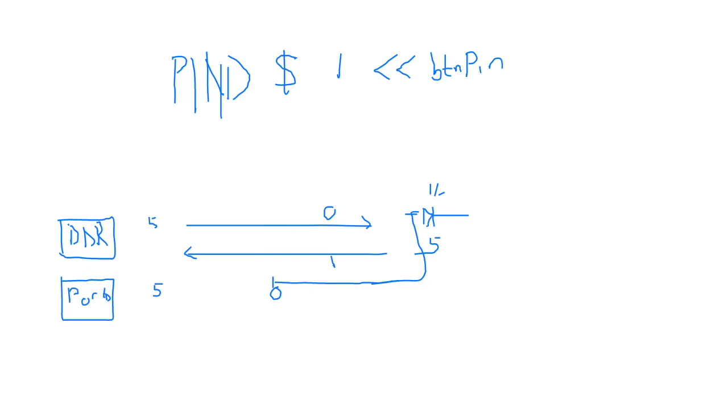Now, if it is an input, you have an input. If you send a 0 to an input, basically you're just connecting it to the ground, so that input is grounded. If you send a 1 to that particular input, which in this case is pin 2, you are simply connecting it to the pull-up resistor, so you are using pull-up, and by default the state will be 5 volts unless you press it. Arathi, I hope that answers the question. And hopefully anybody else who had doubts or did not get what we were explaining.